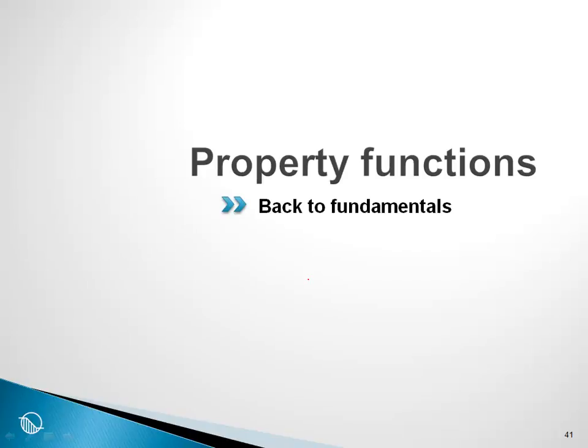Defining the hydraulic conductivity function and the volumetric water content function, generally the property functions, still remain somewhat of an impediment for some users for using SEEP-W. In this session, I will attempt to shed a little bit more light on the subject by illustrating cases where it is incredibly important to define the property functions very accurately, while in other times approximations are more than adequate.